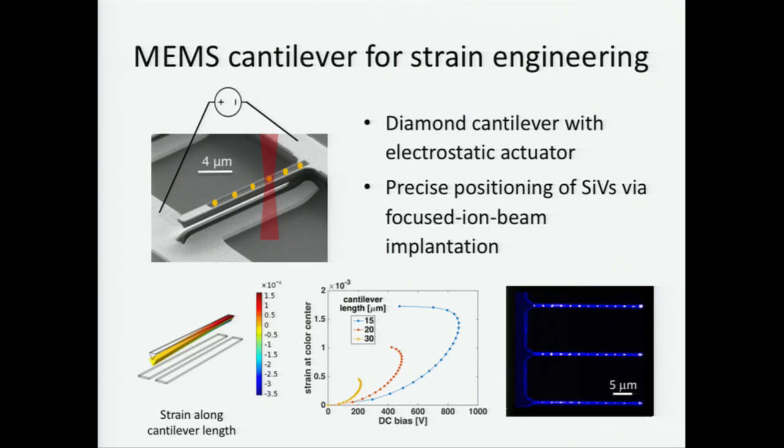The reason it doesn't get destroyed is, first of all, it's in vacuum, so there are no Townsend breakdowns. But there are all sorts of other problems. I used to fail a lot of times with the gold. I looked into why this was happening, and there is always a small leakage current. I think it's going through the surface, so it tends to destroy the gold. Gold is very fragile, especially at this high field. So I replaced the material with tantalum, which has a very high evaporation point. Whenever these electrodes get destroyed, it's eventually all Joule heating. You have very high heating at a local hot spot, and then it bursts, evaporates, melts, whatever. That doesn't happen to a material with a very high evaporation point.